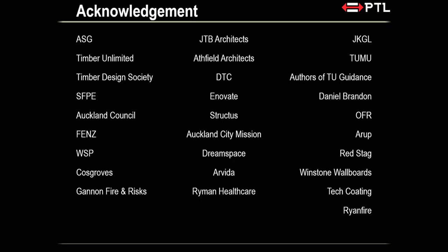But here there's only a 3-story hotel and you want to clad it all in chipboard, and you convince the structural engineers that the chipboard bracing works on the ground floor. Then you get your bracing and your fire rating at the same time, instead of having plywood and then chipboard on top. Often they say that it doesn't work, but obviously it does.